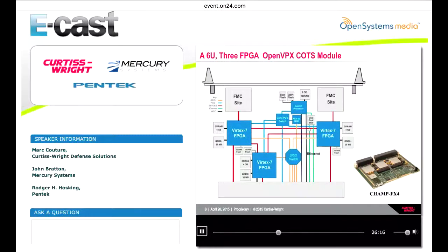This particular architecture shows a couple of Virtex-7s right behind those FMCs to take in the ingest. Sometimes you have 12-bit ADCs that are sampling gigahertz of intermediate frequency. Sometimes it's 16-bit, more channels, more popular in common systems where you need the kind of dynamic resolution required to do a demod, and then you may combine that and move along into the system.